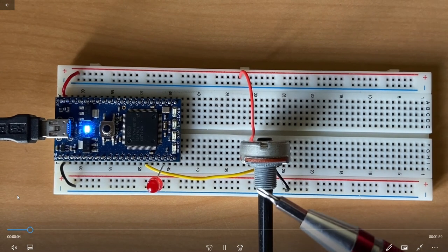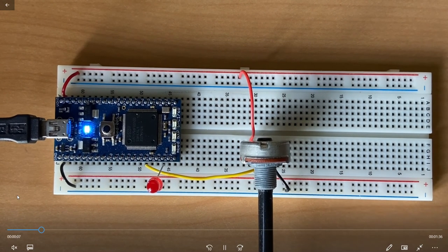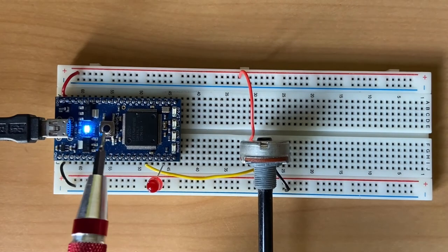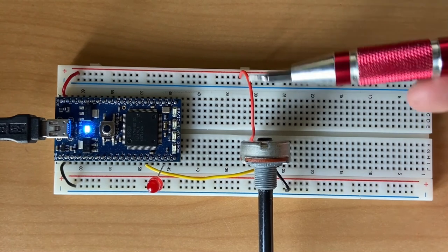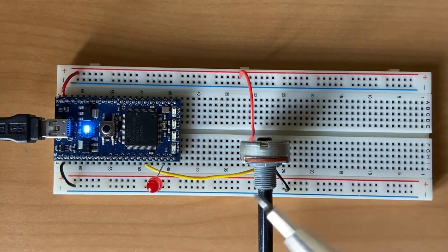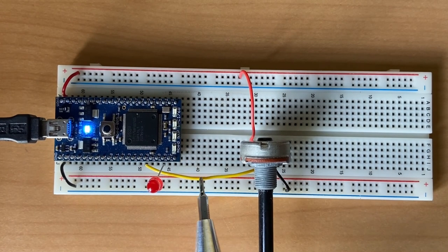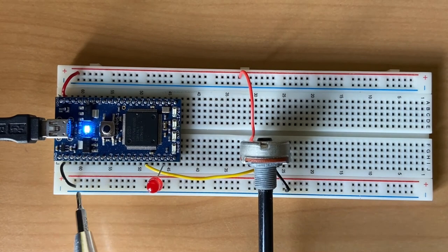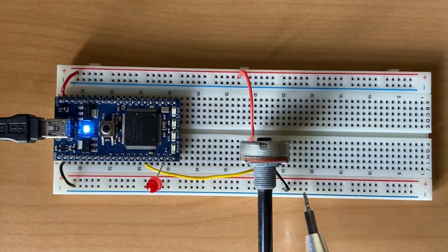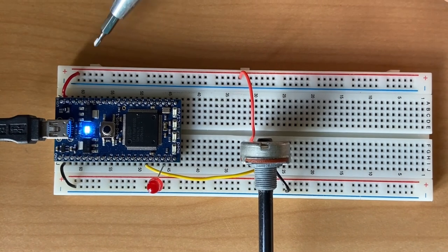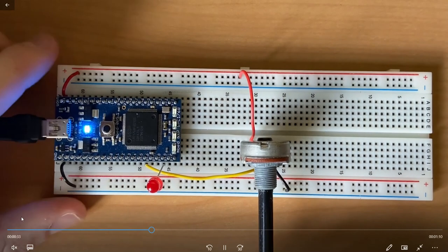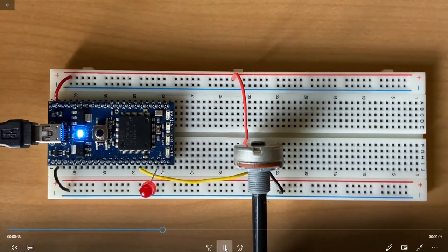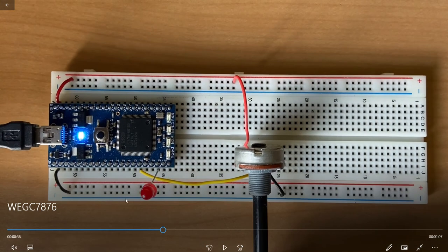I've got our potentiometer, which is going to act as our analog input. I've got an LED, and of course we've got our MBED there. Now the key thing with our analog input, our potentiometer, is we've got a power supply to it, we've got a ground wire, and then that yellow wire is our analog feed from the potentiometer. So we're taking along there 3.3 volts, and then we are essentially grounding it, we're getting the common ground, and we're using, as I said, 3.3 volts.